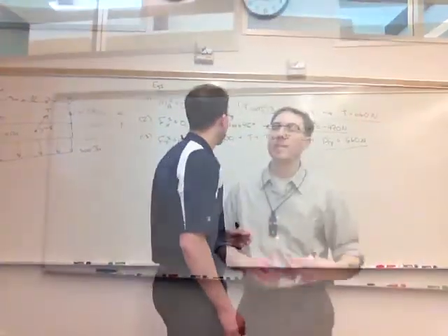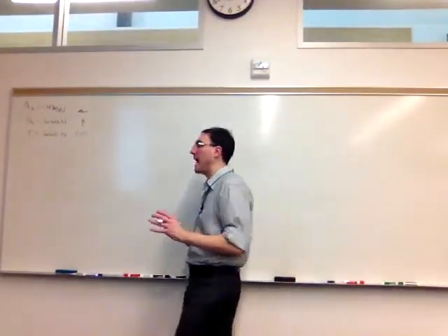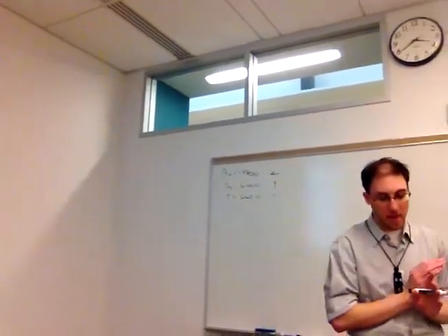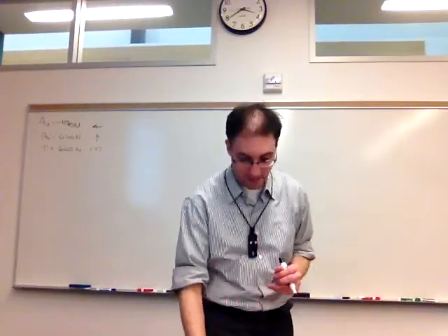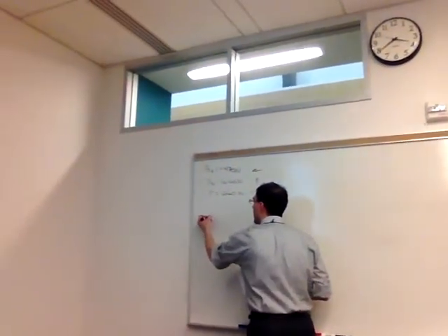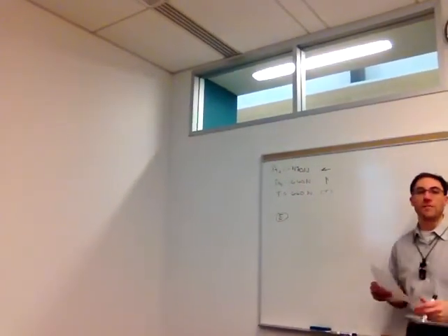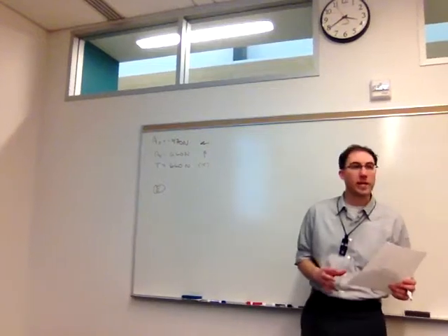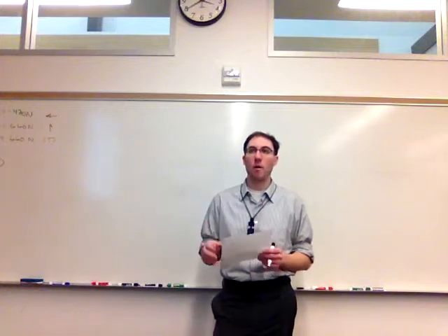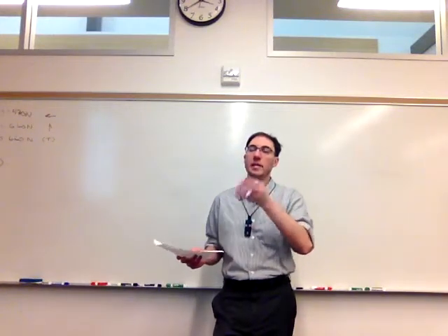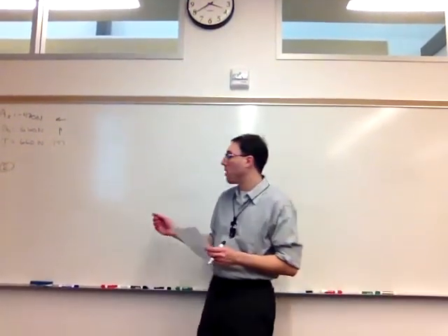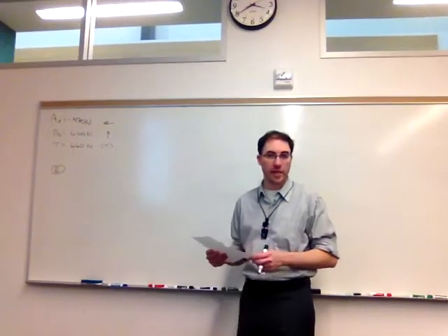Now, we're interested in finding the internal reactions at E and at F. And we're going to take vertical cuts here, or transverse cuts to the beam to do that. We'll get into the other types of cuts later. Let's begin at E. We don't have to worry here if we're just to the left of E or just to the right of E. We only have to worry about that if there's a point load or an applied point couple on the point that we're studying. E has no point load or point couple. There is a distributed load, which we have to account for, but that won't change if we're just to the left or just to the right of E.